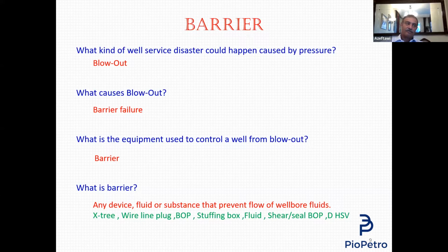BOP stands for blowout preventer. The blowout preventer prevents the flow of hydrocarbon. Fluid: if you create a fluid on top of the formation downhole, and this fluid creates hydrostatic head greater than the formation pressure, then it's a barrier.